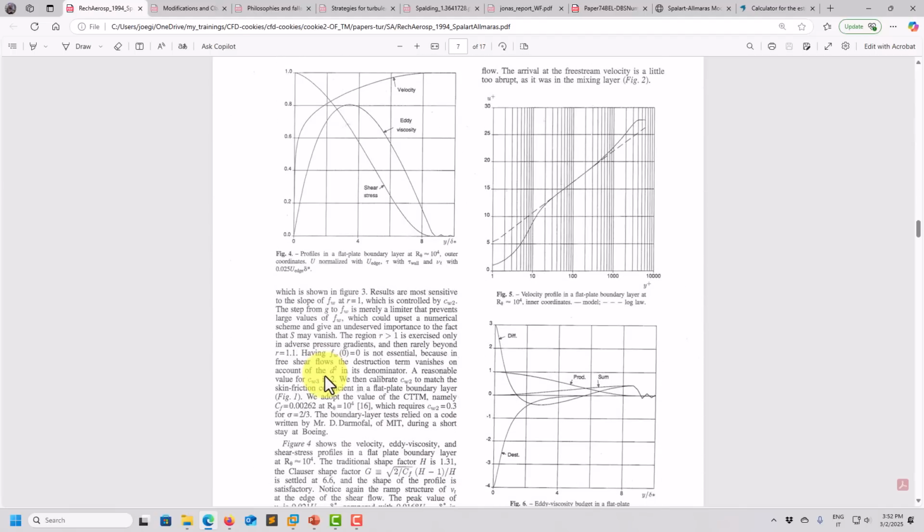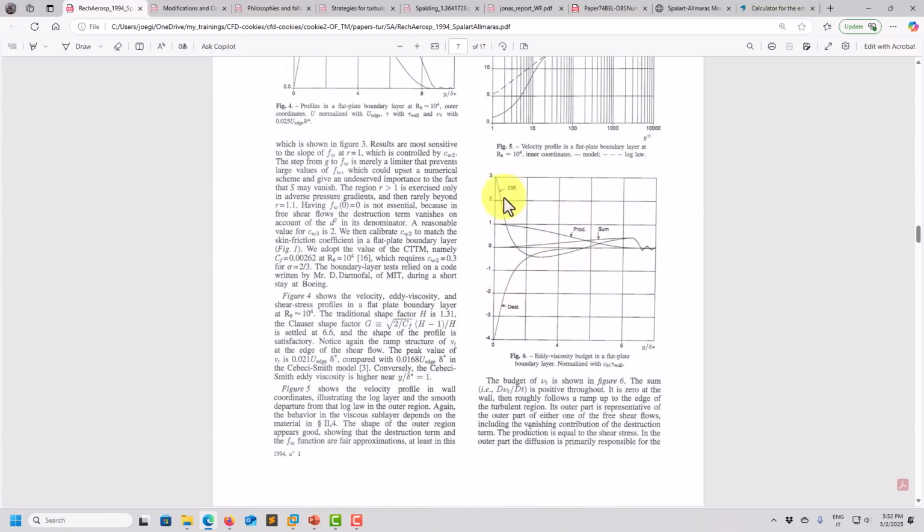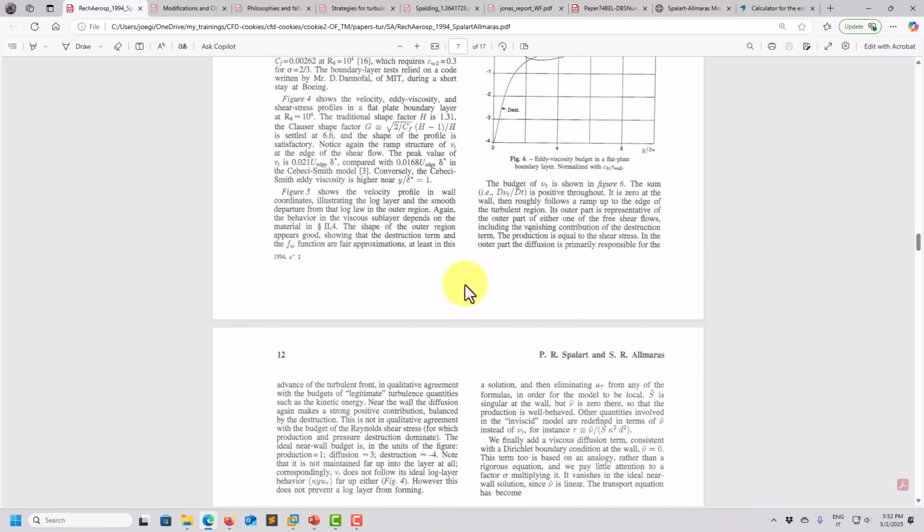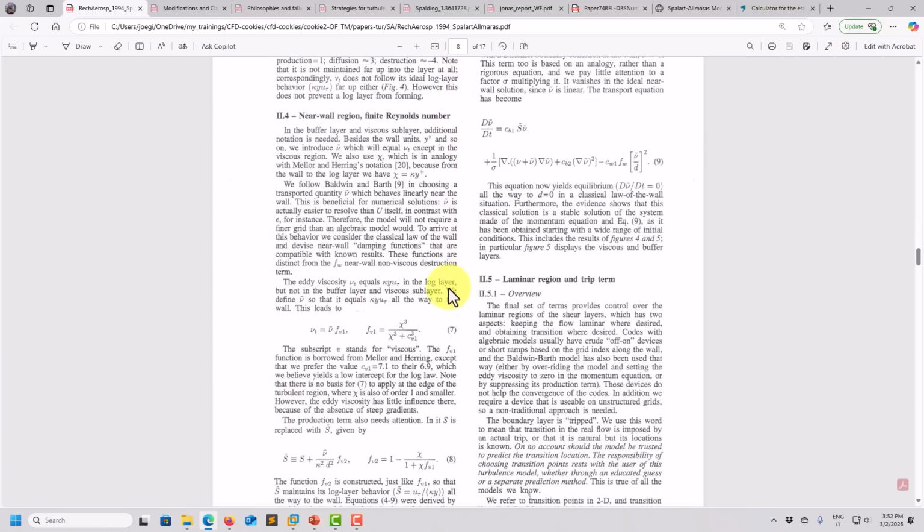So this is the importance of knowing what is happening. Like this, in this model, all the quantities that take place in your transport equation will have slightly different behaviors, okay, but similar to the observations that we have done so far. You will see those observations, production, destruction, and so on. Then, okay, the model comes in different forms, as I mentioned, with many corrections. You have near wall, then you have wall function treatment, and so on.